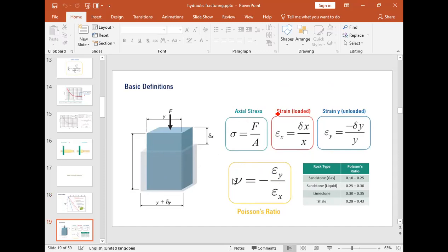So when you apply stress on a material, that material compresses. As it is compressing, it is extending in the y direction, because I have two directions here. I have probably my y direction, and in this case, they have called it the x direction. We have the x direction here. Then we have the y direction, which is in the horizontal manner. So as you are compressing the material, it is not only compressing in the x direction, but it is extending also in the y direction.